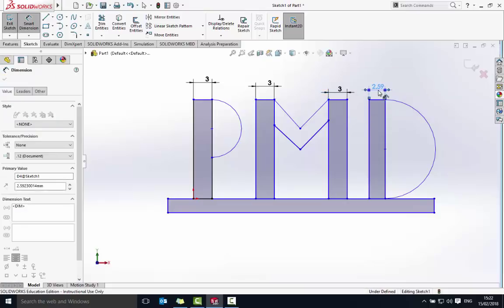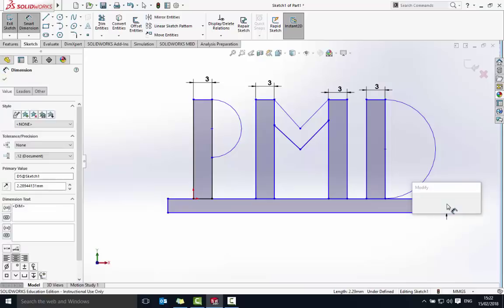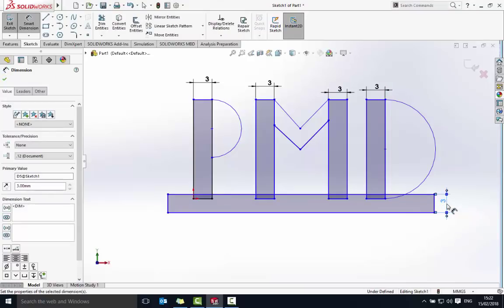Now remember, when I'm doing this, the gold standard that everything is fully dimensioned is down here. It will say fully defined. So when I'm putting in smart dimensions, really I want to keep going until that says fully defined. If there's something really fiddly and you can't find it, it's not the end of the world. You can go on, you can do all the other bits, but it is nice if it does say fully defined. So let's have a look. What's next?